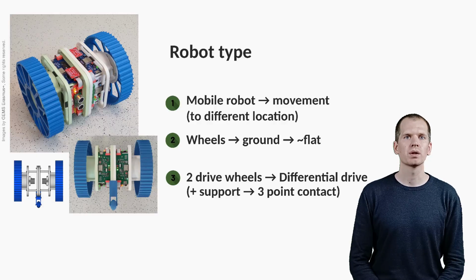To achieve movement, the robot has two drive wheels, and each wheel rotation is independently controlled. If the two wheels rotate with exactly the same speed, the robot will move in a straight line. Otherwise, it will travel on an arc. The difference between rotation speeds of the two wheels determines direction of travel, and that is why it is called a differential drive. The same concept also applies if instead of wheels, the robot would use two similarly oriented propellers or tracks.